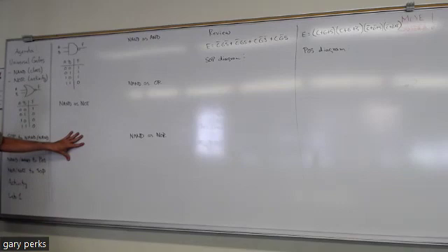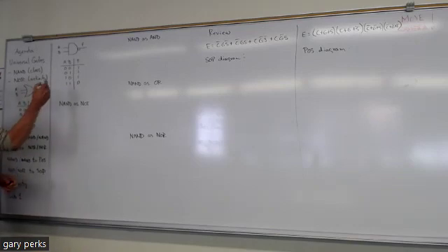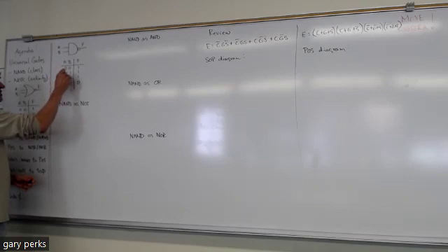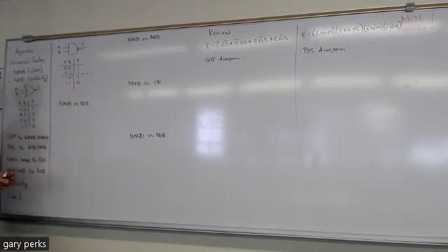Well, there's actually two different ways to come up with having a NAND gate act like a NOT gate. And remember, a NOT gate, you just get the opposite out of what's going into it. So one way that you can see that a NAND can be used as a NOT is that if I divide this truth table in half, and then I only look at the bottom two rows. So just pretend the top two rows aren't there. If you just look at the bottom two rows, can you see what these bottom two rows tell us?